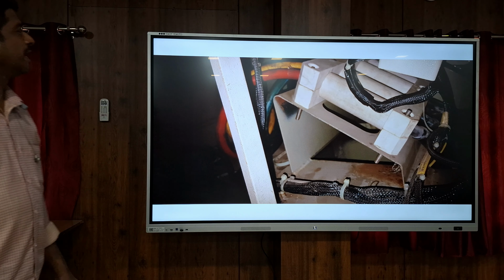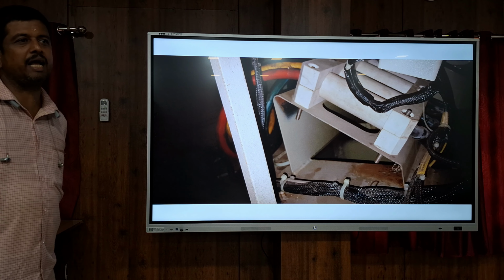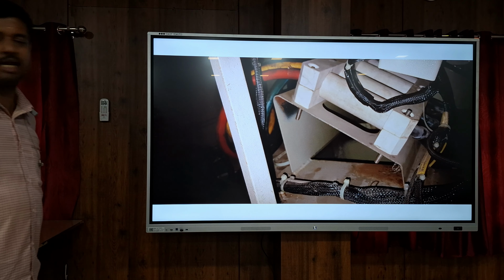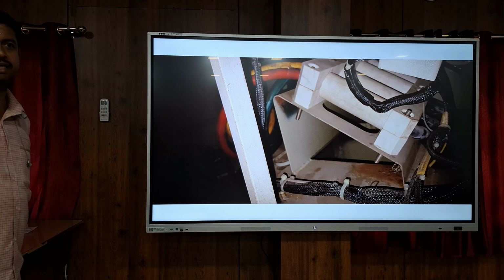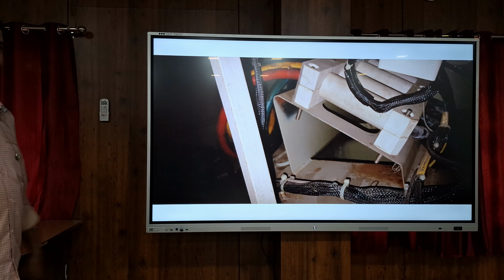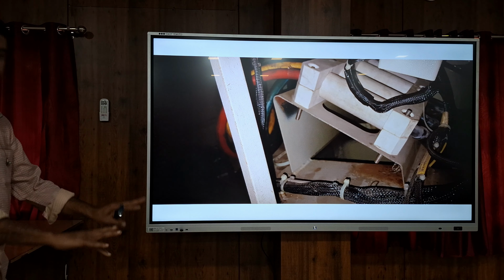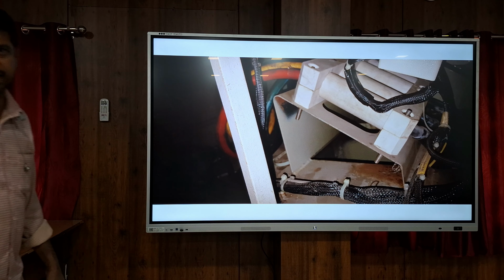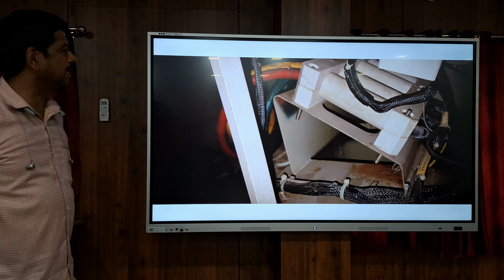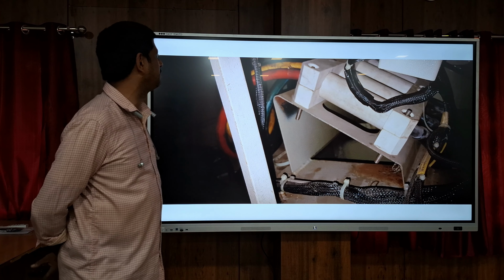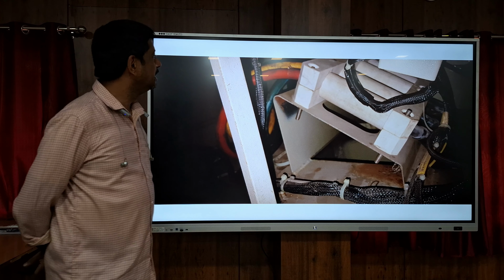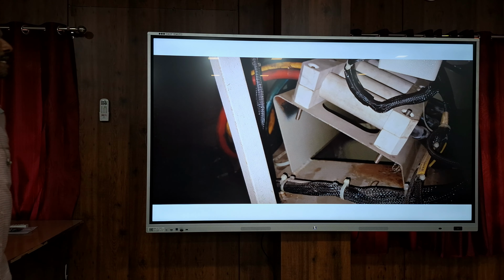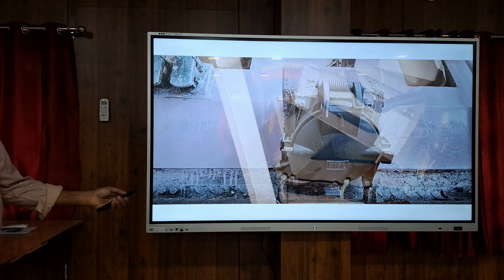This is the connection below both cab LP and ALP seat. That is, when LP and ALP sit in front, they place their feet in that area. Behind or under that, there is an electrical connection, which is with the 750 volt supply to the power car. Its name is hotel load disconnecting. This junction name is hotel load disconnecting.